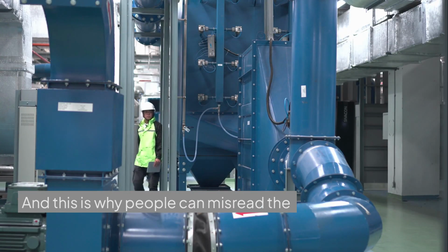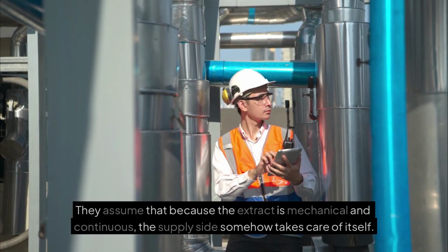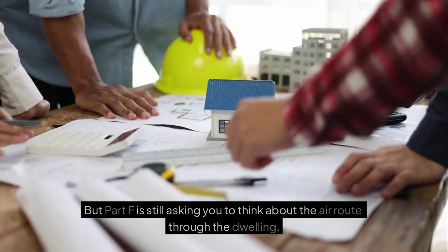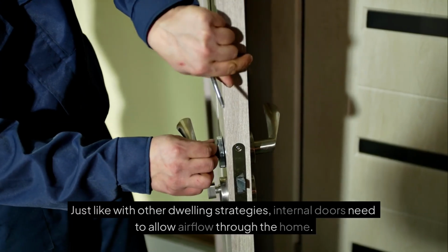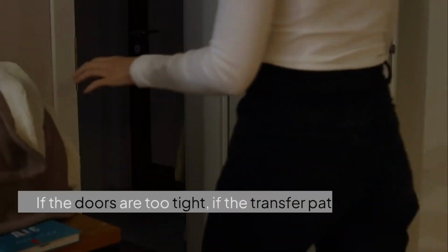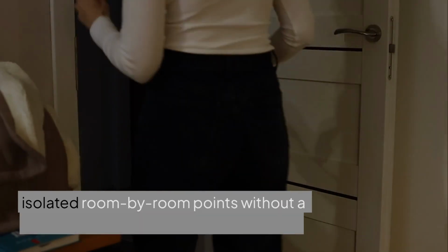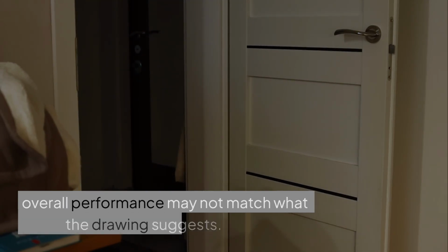And this is why people can misread the strategy. They assume that because the extract is mechanical and continuous, the supply side somehow takes care of itself. But Part F is still asking you to think about the air route through the dwelling. That includes internal transfer too. Just like with other dwelling strategies, internal doors need to allow airflow through the home. If the doors are too tight, if the transfer path is ignored, or if the system is designed as isolated room-by-room points without a proper air movement strategy, then the overall performance may not match what the drawing suggests.